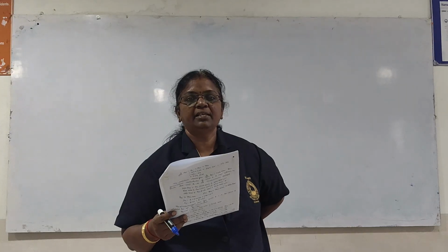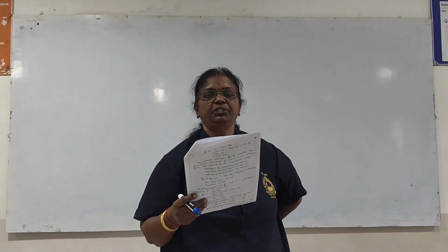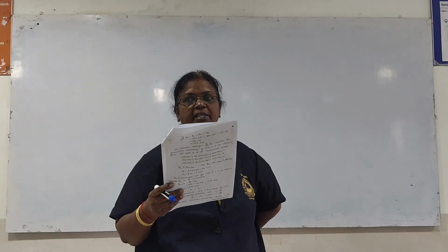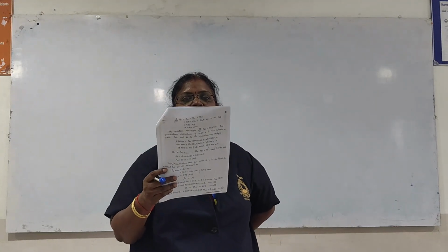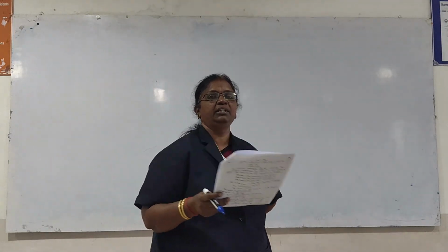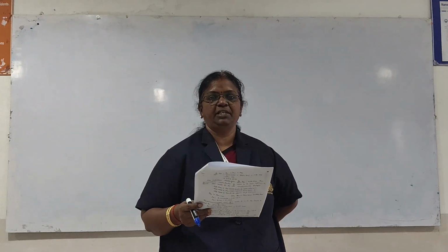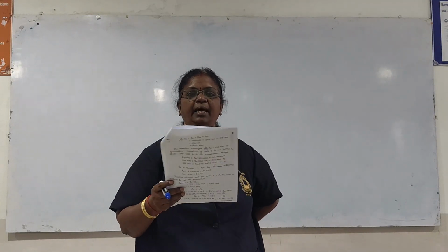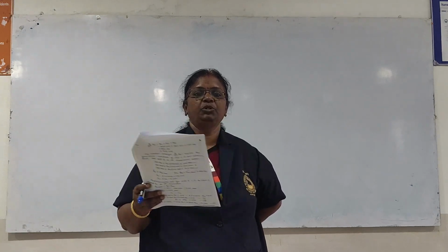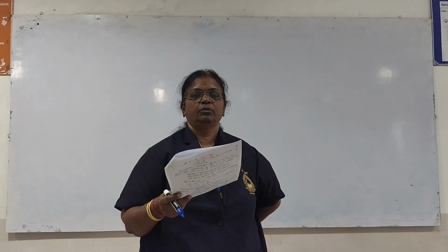Here Bi is the coefficient of Pgi, and ai is the coefficient of Pgi square. Then using the value of lambda, we have to calculate Pg1, Pg2 and Pg3. So Pgi is given by the formula lambda minus Bi by 2ai, where i is the ith unit. Here in this problem we have 3 units.